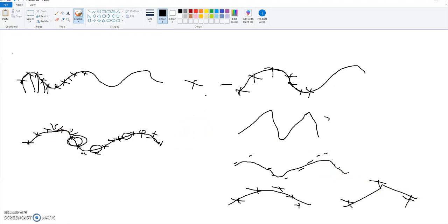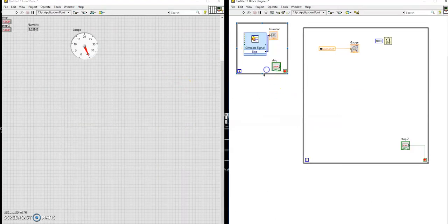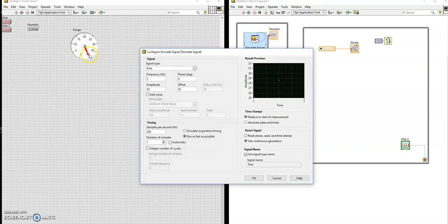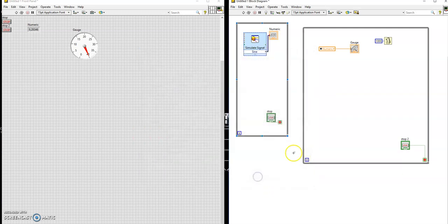So remember I said we're going to generate 2 sine waves. So let's make those 2 sine waves here. We're going to make the information one, the one that's making our 2 Hertz value going from 0 to 40. We're going to make it at a sample frequency of 200. You can make it much higher, it doesn't matter now, but I'm going to stay at 200 with one sample, one value.